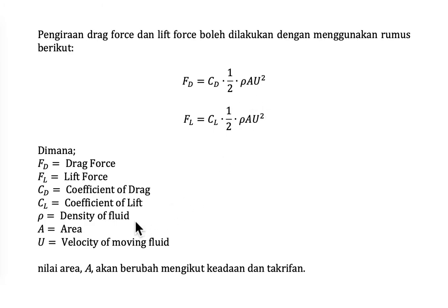Rho is the density of the moving fluid, A is the area, and U is the velocity of the moving fluid. In these situations, please make sure that sometimes we need to take the projection area for this calculation, not its real area. We will discuss that later on.